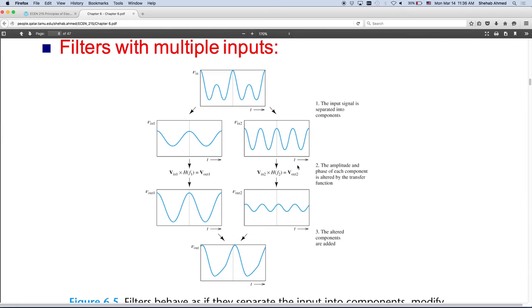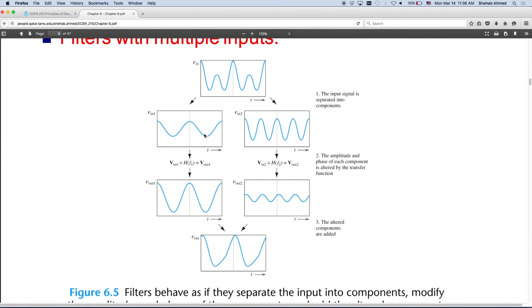That's a transfer function. Right? So what happened here? This signal happened to be translated to this signal. This signal happened to be translated to this signal. So what is this block doing? This is obviously a low frequency signal. What happened to the low frequency signal? Its magnitude was amplified. How about the high frequency signal? Two things happened to it. The magnitude changed. The magnitude was damped significantly.